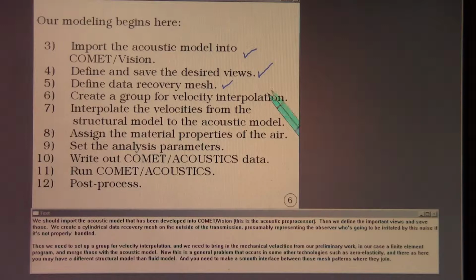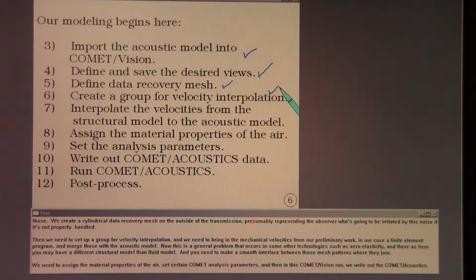Then we need to set up a group for velocity interpolation, and we need to bring in the mechanical velocities from our preliminary work, in our case a finite element program, and merge those with the acoustic model.